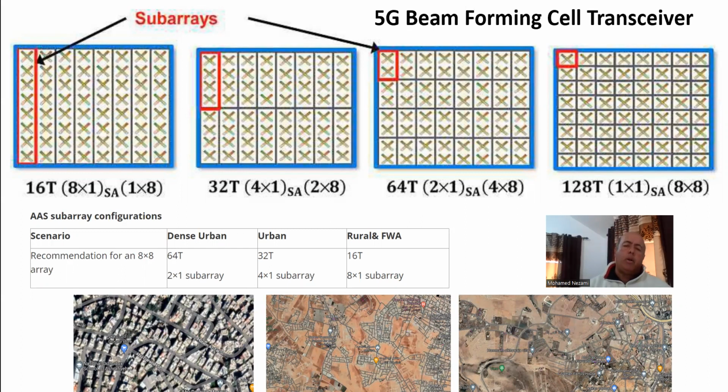I'm really doing a hardware design. I'm trying to demonstrate the RF components. I'm going to pick RF components off the shelf from semiconductor manufacturers to build a transceiver for millimeter waves at 28 gigahertz plus or minus 200 megahertz bandwidth. But the reason I'm doing this is because I want to show you why what's coming up ahead. We need to understand the system so that you can understand why I'm designing this.